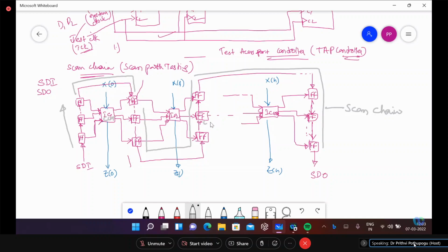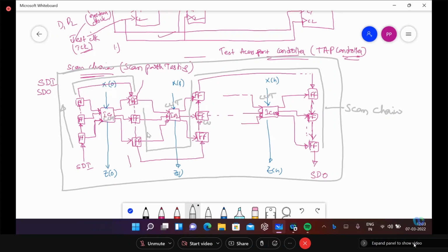test, if you are taking, sorry, this one, circuit under test, and this is circuit under test, a repeated sequence you are taking. Now, if this is for one IC, an IC having this much complexity inside, I name it as one IC. Another IC I want to test, another IC I want to test, plenty number of ICs I need to test, means that I need a segment of these scan registers, okay, and the ICs under test, different ICs.